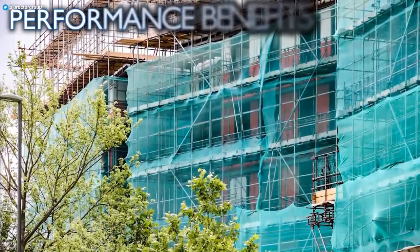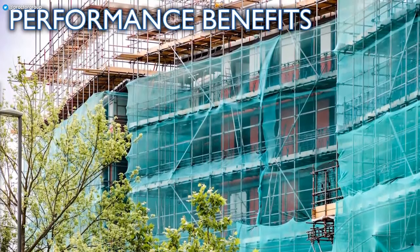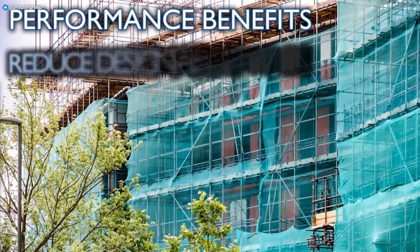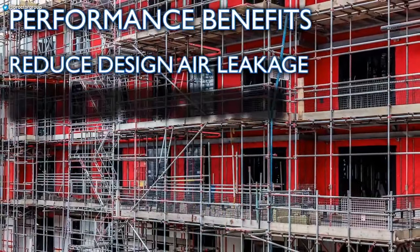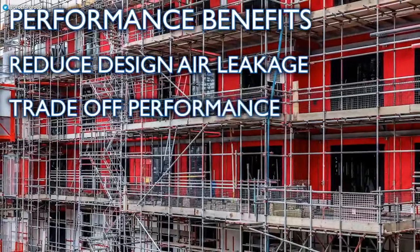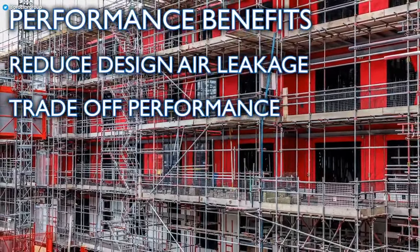So now let's consider the benefits of this more reliable air leakage performance. If we can be sure we'll achieve a low rate of air leakage, then we can reduce the design air leakage rate used in our modelling, which means we can reduce our requirements in other areas. In a recent project we were involved in, this improvement in air leakage was traded off against the fabric insulation.